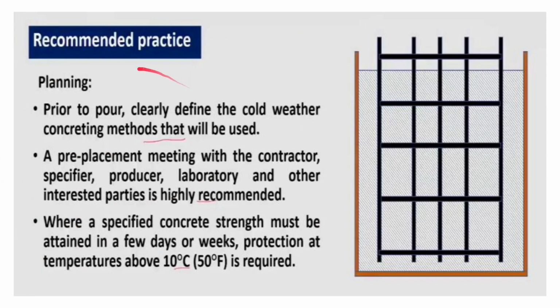Apart from that, some of the planning practices which are recommended are such that prior to the pour, we should clearly define the cold weather concreting methods which will be used. We need to have a pre-placement meeting with the contractor, producer, specifier, laboratory, and other third parties, so that it is quite efficient and saves our concrete from the ill effects of cold weather.